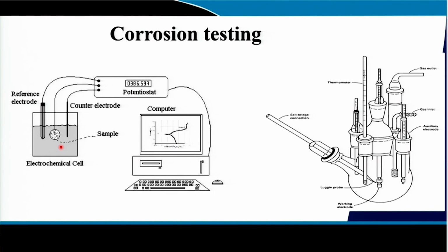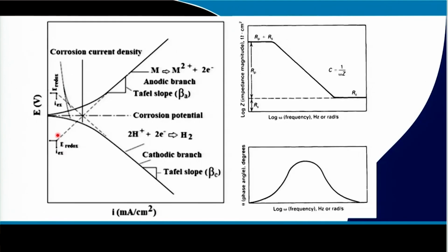which is a little bit nobler than the equilibrium voltage. So, a little higher than the standard open circuit potential of the component, and then you just go on passing electrical current. You will find that you go on applying the voltage. For example, you can change the voltage from a value a little bit active of OCP to much nobler than OCP.